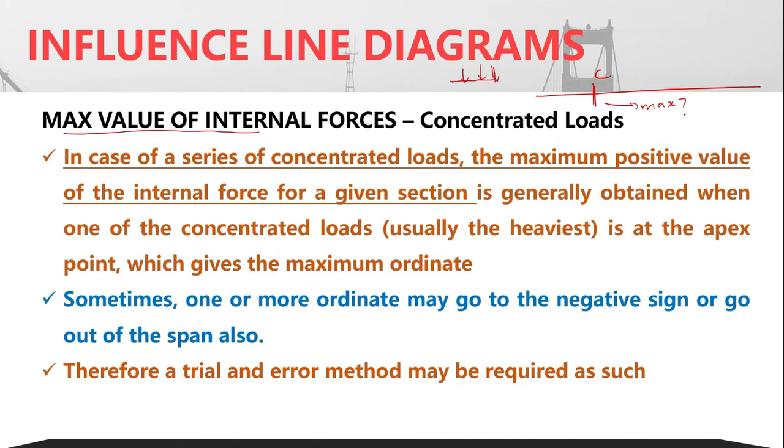Now in case of a series of concentrated loads, the maximum value of internal force occurs when the concentrated load is placed at the maximum ordinate.